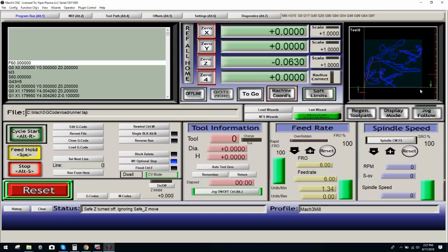And you can see when I'm jogging down now, I'm past the center point. You can see that from that horizontal line. And we're jogging down. And the thing to keep in mind with your Z is you have two ways to set your Z soft limit. You can set it with, if you're doing a lot of repetitive work with your end mill, the thing is always to keep in mind that your Z is never typically going to hit the table anyways.